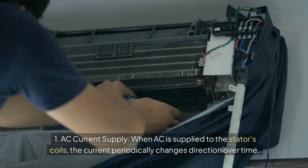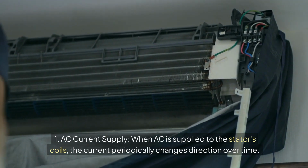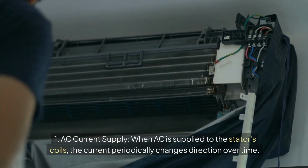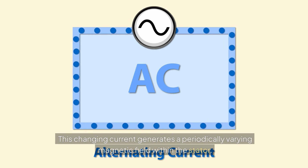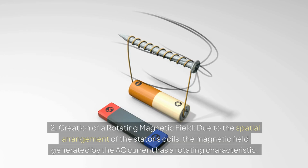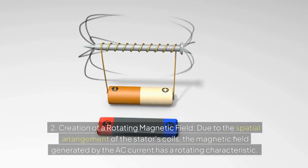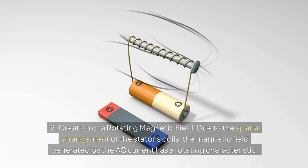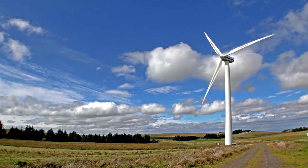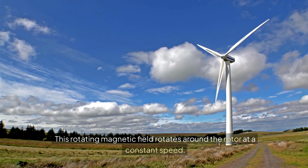2. Operating principle. The operation of an AC motor involves the following steps. 1. AC current supply. When AC is supplied to the stator's coils, the current periodically changes direction over time. This changing current generates a periodically varying magnetic field within the stator. 2. Creation of a rotating magnetic field. Due to the spatial arrangement of the stator's coils, the magnetic field generated by the AC current has a rotating characteristic. This rotating magnetic field rotates around the rotor at a constant speed.